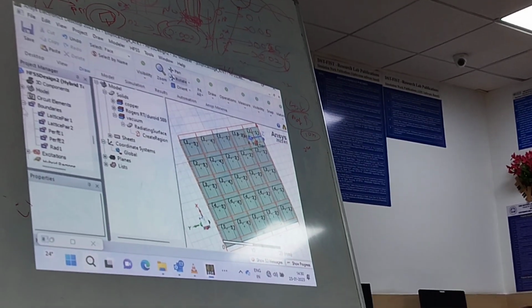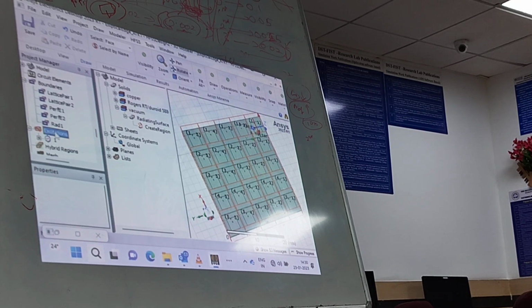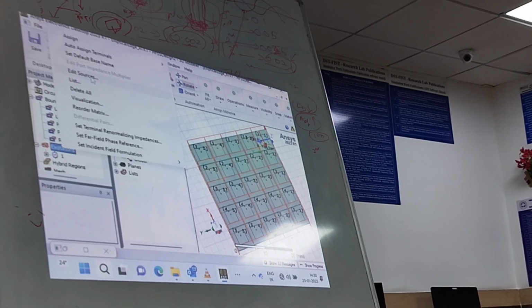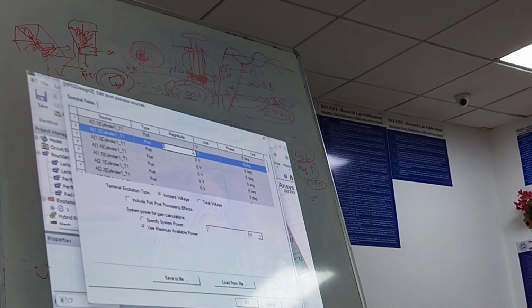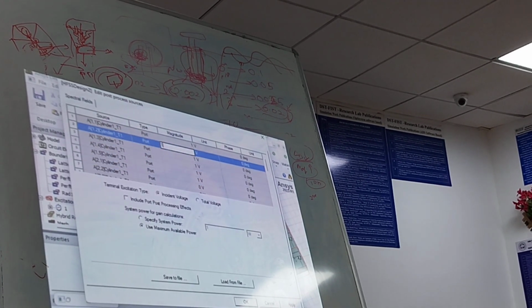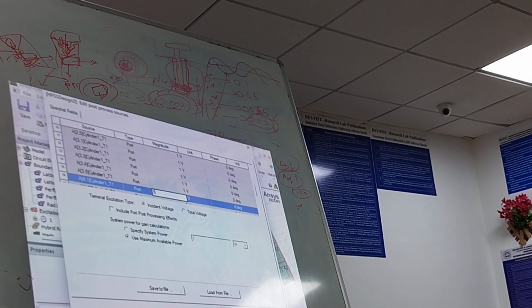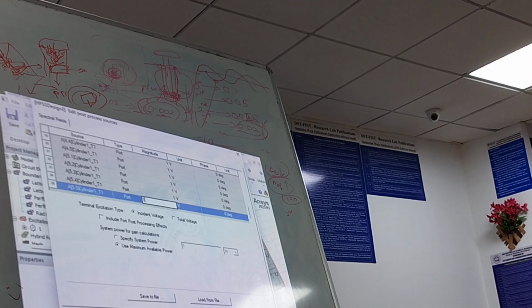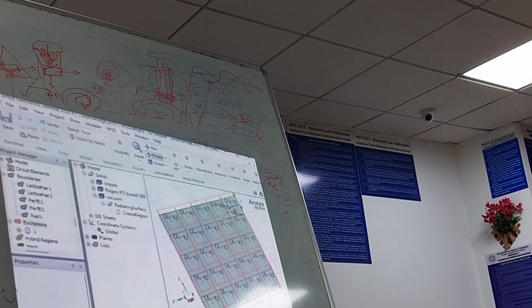The simple change I am going to make here, first thing, is excitation. I have to excite all the structures. Without the beamforming application or using the toolkit, we'll just go ahead to edit source. I'll change the input to 1 volt for all. We'll see if I excite all the elements, whether my gain is improving or not. So I'll apply and click OK.